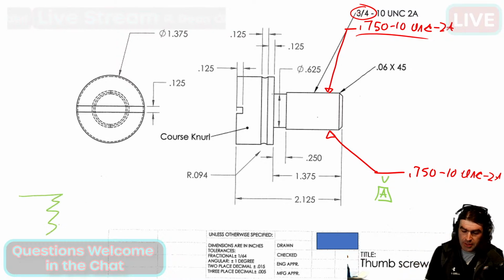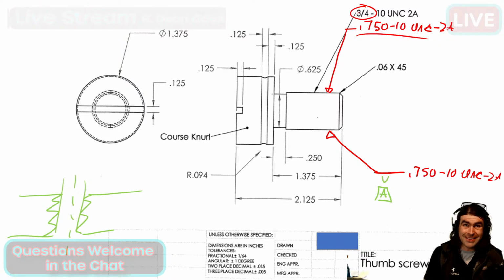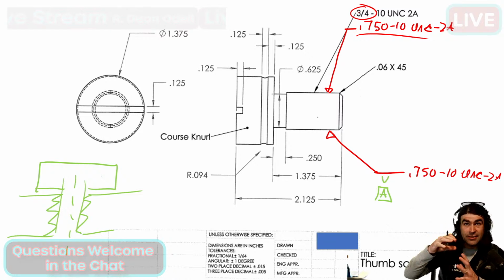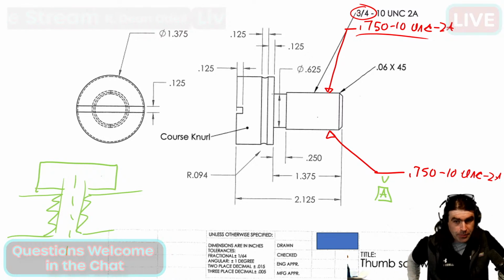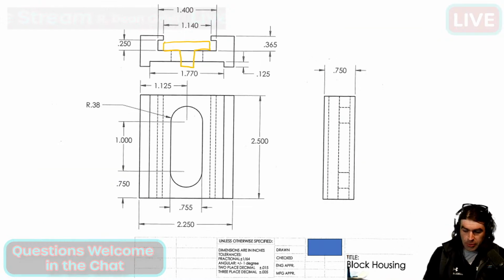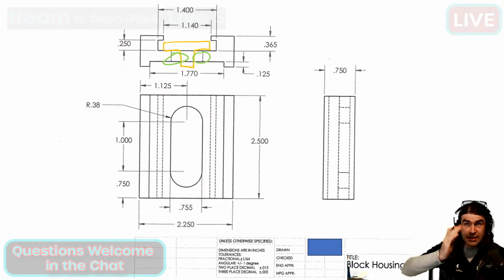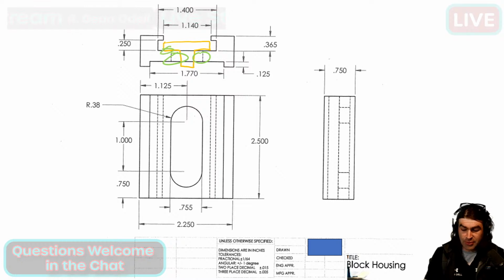So, if we have a threaded hole and we thread a fastener in there, it's going to be the shaft of the fastener, the axis of that locates this in space, not the head of the fastener. That is only going to get one point of contact because it already is being located by the thread. Not in our case here. So when this thread sits in here, there's going to be clearance probably here. And in any case, it's not going to set the orientation in space. What's going to set the orientation in space is this flat.